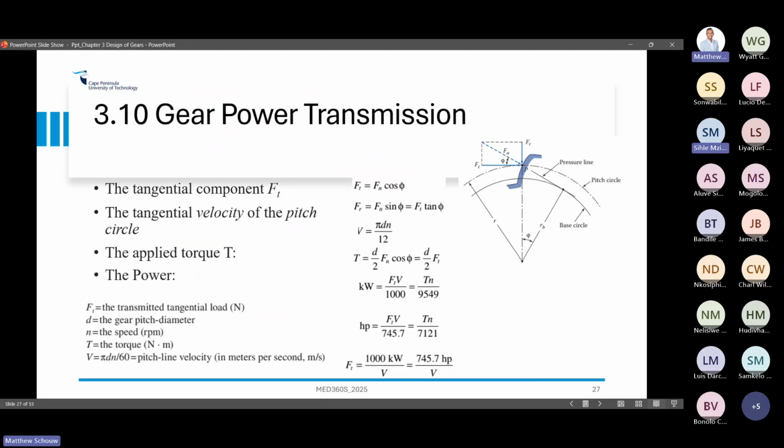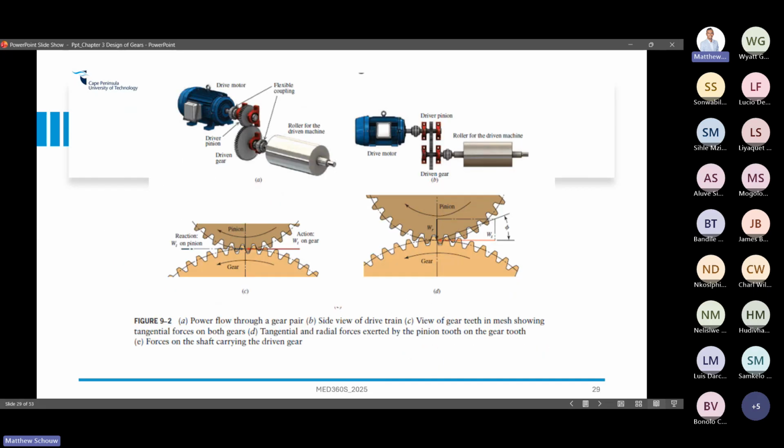Where it's coming from is that we have a resultant Fn of the two gears in contact. All we're doing is taking two components. One is the cos component, the tangential force, which is producing the torque. Then we take another component, the sine one, which is the radial force, separating the two gears. Okay, so it's some kind of geometry. Yes, trigonometry of components or vectors.